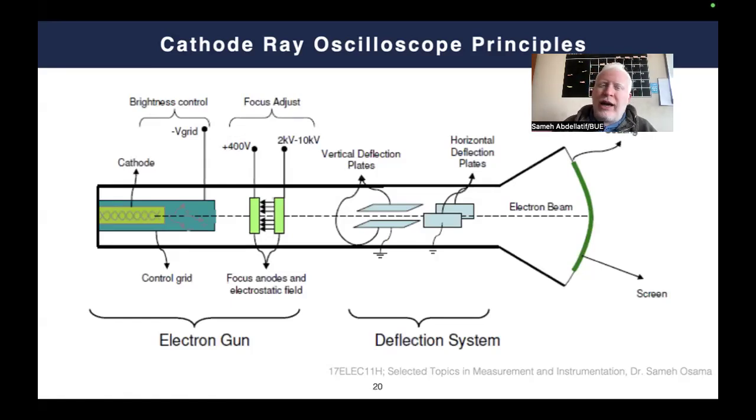First, as I mentioned, we have what we call the electron gun. If you go to the theory of solid-state electronics, you can understand that you can have an electron gun whenever there is a device or a material that can emit electrons, by giving this material an energy greater than what we call the work function of the material, so that the electrons escape from the material and go to the outside environment with a high speed, which, if you remember, we call the affinity level, the last state in the material.